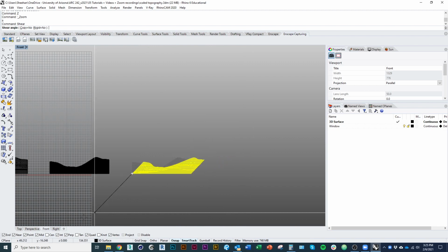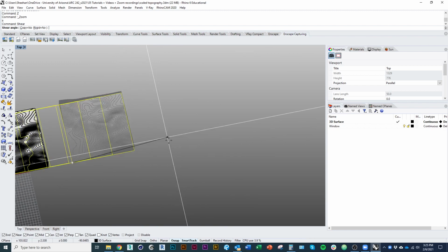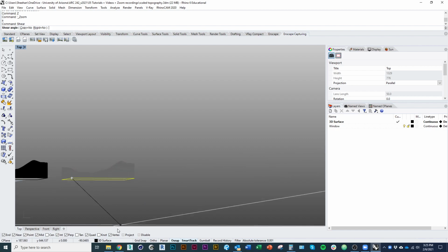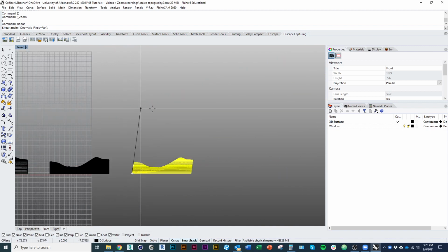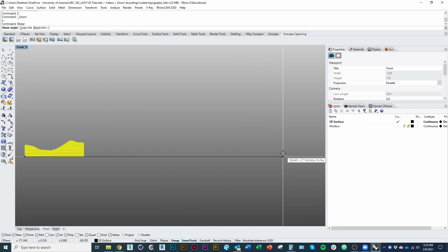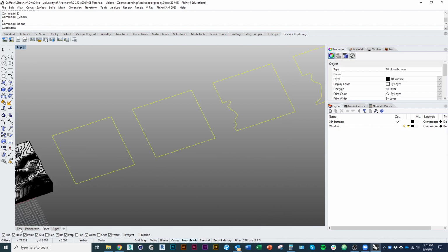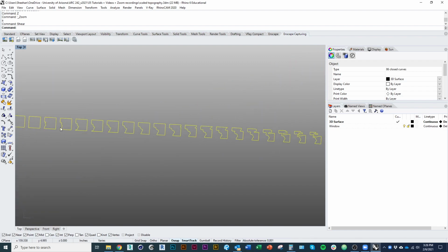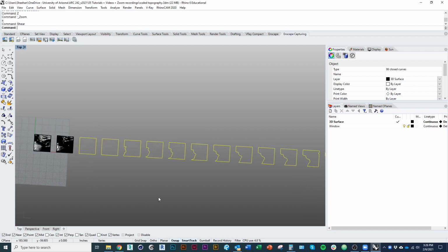And then I can actually go back into top view so you can see what I'm doing here. I'm going to drag my mouse over to the right. You can see what I'm doing here is I'm separating them. Do it in side views, as you see. So what I want to do is go far enough that every single layer is going beyond the previous one. Okay, and then if I go back to top view, you can see I've just laid them all out equally spaced in sequence so that I could then go and start to position them in my cut file.